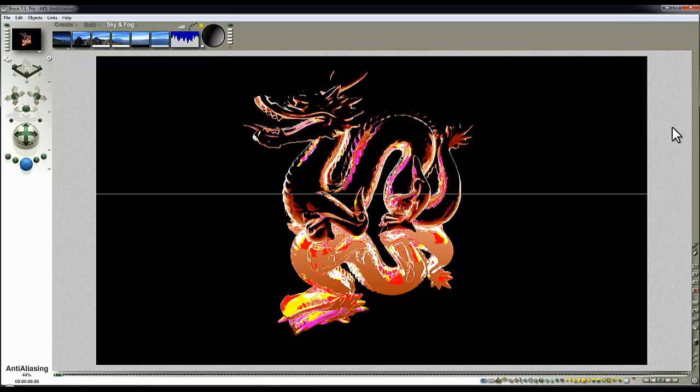Obviously, the more you use this material in objects around your scene, the more light will be generated by this process, and the more light will appear in your scene. Because it's reflection, it has an overhead in terms of processing, because it's got to calculate all the light bounces off the reflective surface. But because it's using no direct light or specular light, it's fairly efficient because it's not calculating any shadow region. So it gives an interesting effect on the material surface, and an effect that I'm not aware can be created in any other way other than exploiting this process that allows you to create a very high output.